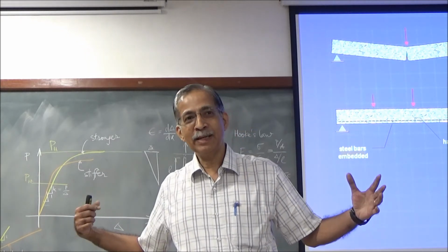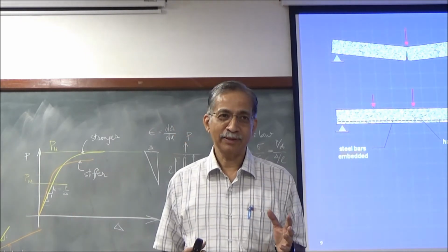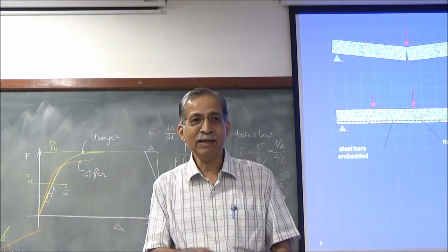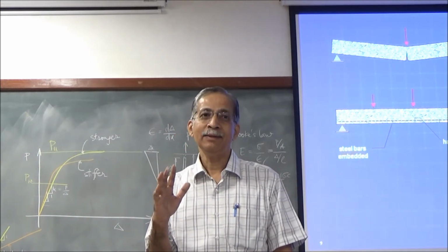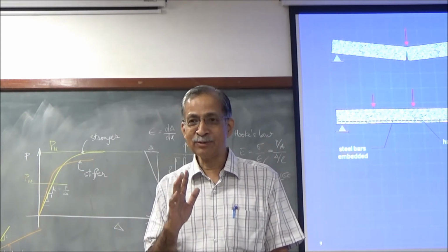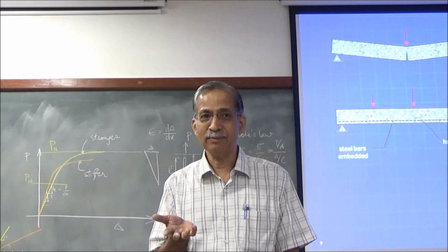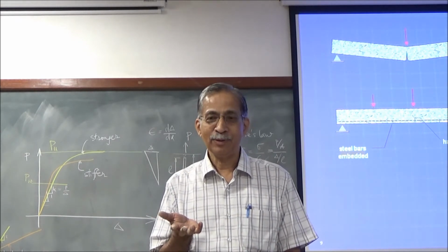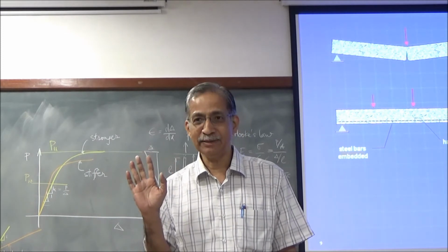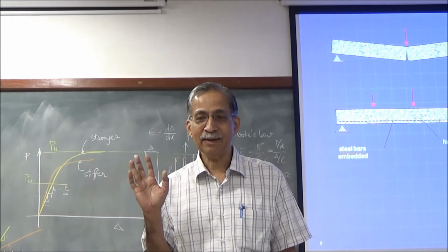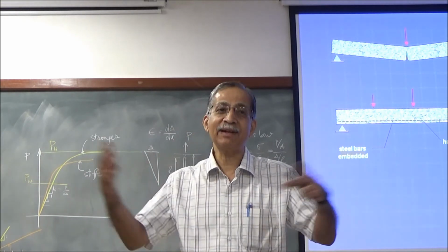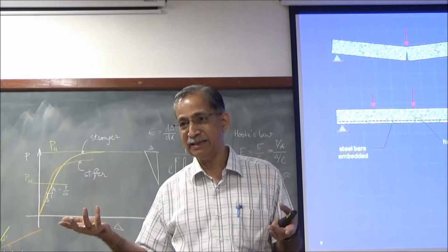See, the earthquake is pumping energy into the structure. The structure, if it were to behave elastically, will store that energy and release it. But the amount of energy is so huge, it can't do it. Right? So it'll break. There must be some way to get rid of that energy. That energy is got rid of through many ways. Extensive cracking will release energy.